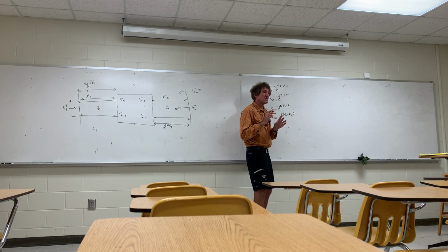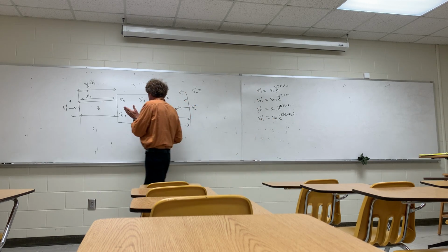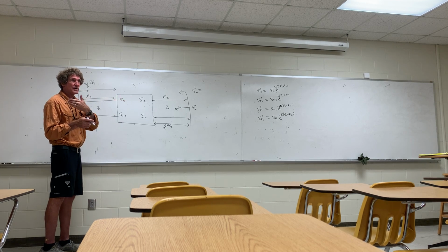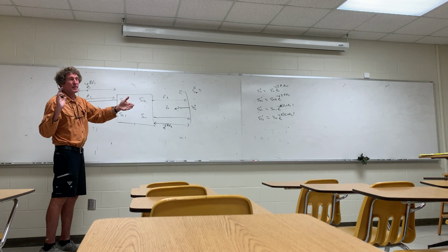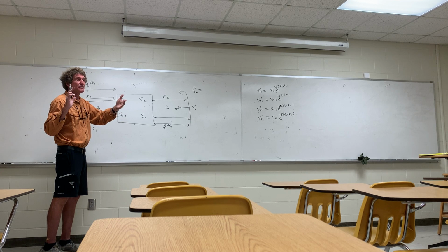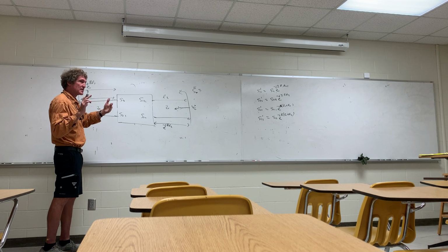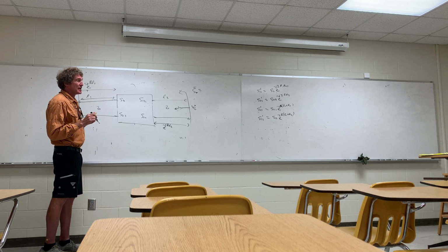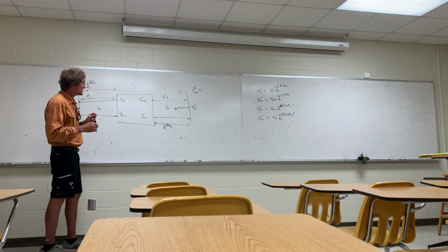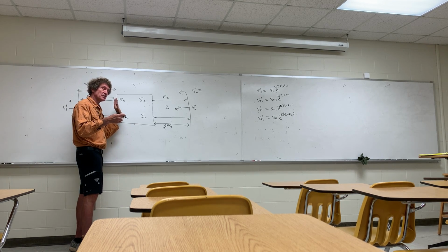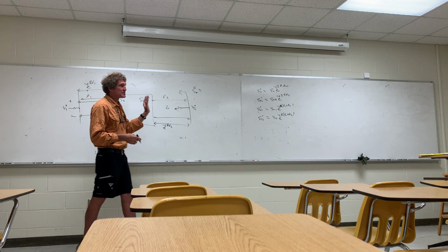Beta changes with frequency. And what we did is, we got the S parameters for this system, and we measured it over a swath of frequencies, I don't remember the exact range, say from 8 to 12 gigahertz over X band. So we have all this information about the device, basically the S parameters. Now, based on that, we know how to write the equation for transmission and reflection, assuming we knew what the epsilon value was. Follow me on this? You can do this. So we had these equations.